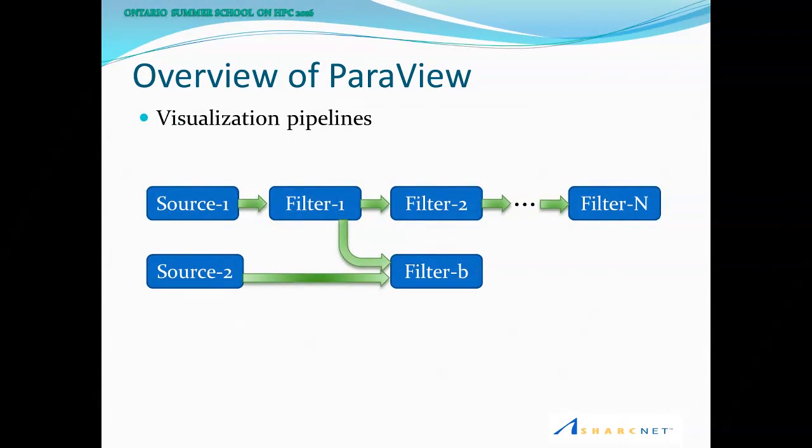Okay. So before we start exploring ParaView, I'm going to introduce two important concepts. One is pipeline. So what is a pipeline? The philosophy of ParaView is like this. You load in your data by some reader. The reader is called a source. So you load your data into ParaView, and afterwards you can show your data in different ways.